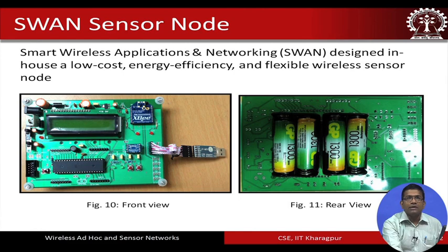It depends on the application and the nature of the requirements what type of communication unit is going to be used. For sensor to sensor node communication, typically ZigBee is good, but from a sensor node directly to a base station, some long range communication such as Wi-Fi or GSM is better.